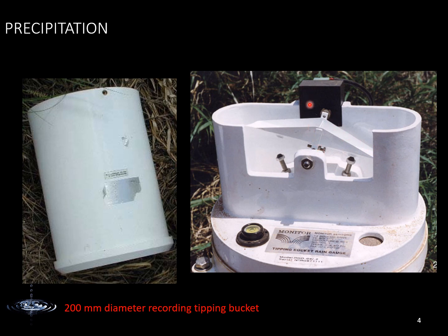And when the water starts to drop here, the weight of this part of the bucket starts to get heavier, and eventually at some point it will go down and hit the sensor here, and it will count as one. Okay, and then when it hits here, the other bucket goes up, and then that starts to collect the rain.